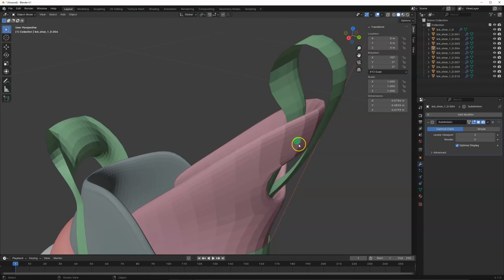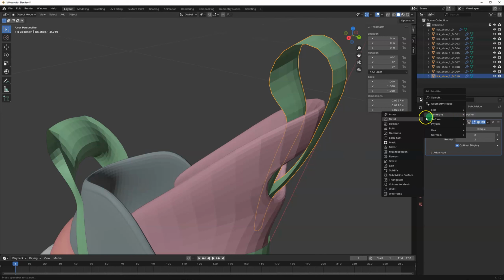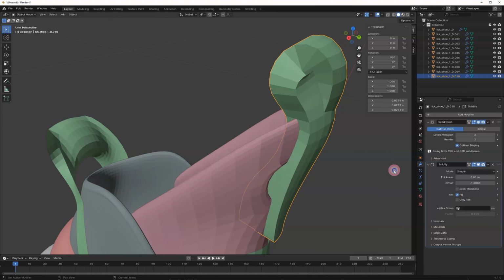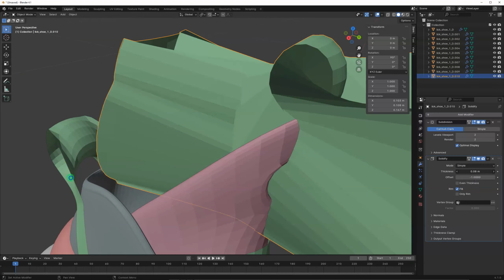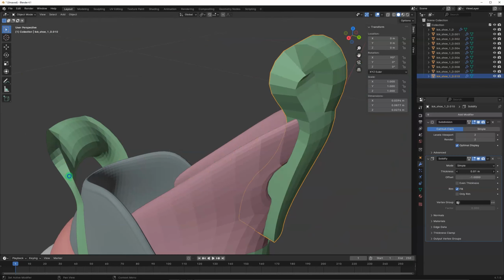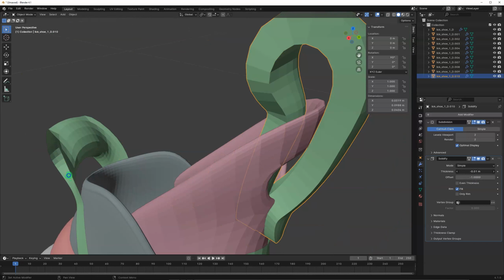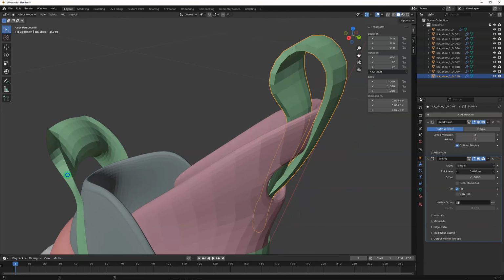So here we've got a surface, and in the modifier, for this object, we're going to add a modifier, and we're going to add a Solidify. It's basically a thickening modifier. And we're going to change its thickness. Now, the best thing to do is, you can see how fast it changes. Press Shift, and then Shift gives you more control. Okay, so now we're at 1 millimeter. Yeah, 0.001 of a meter is a millimeter.